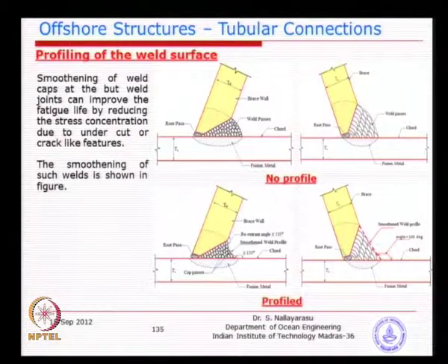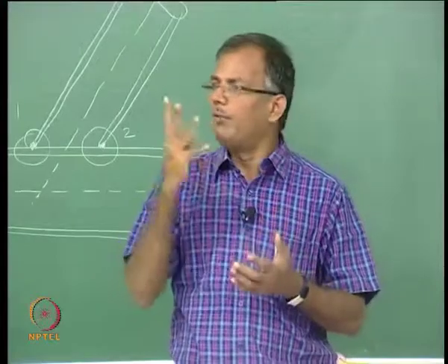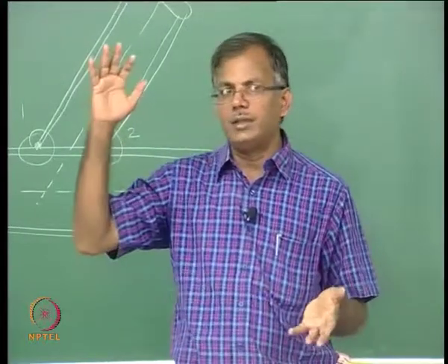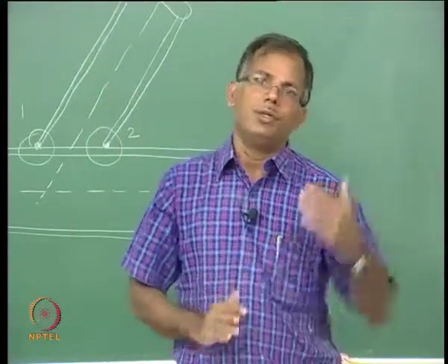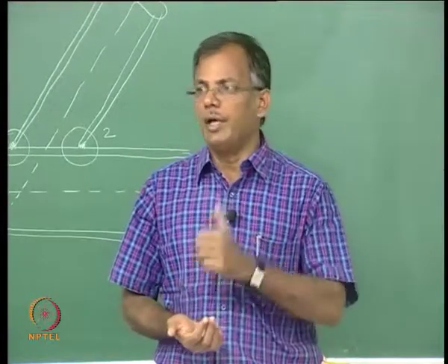Now, if you are able to reduce the stress concentration from 9, 10 to 2 and 3, you have a threefold reduction. When you have a threefold reduction in the stress concentration factor, you will see that the design life can jump very fast, which is a very good idea.